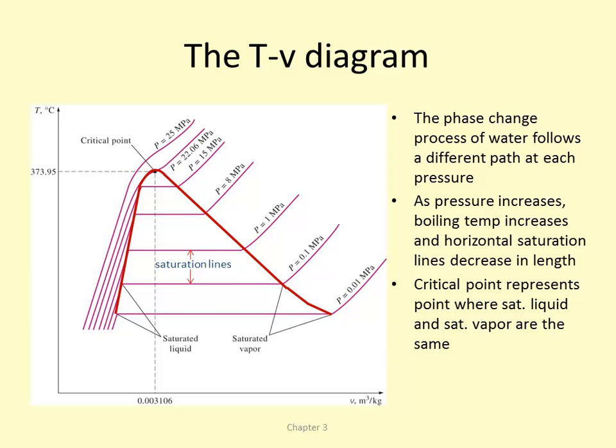So physically understanding what it means in terms of enthalpy, that's the amount of energy that's required both to increase the internal energy of the substance to the point where it's moving, and then it takes into account the expansion of the substance as it changes form. So it's a constant pressure process. We increase the internal energy and we increase the specific volume. So the enthalpy takes into account both those two terms as we vaporize a substance.